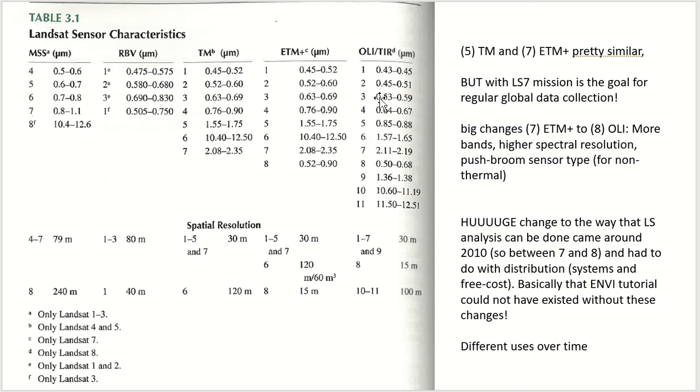And so these have to do with more bands. The bands don't match up neatly because there's a coastal blue, coastal band here, observing reflectance over a rather narrow wave band, 0.02 micrometers. Band 2 in OLI corresponds to band 1 in TM and ETM+, a little bit narrower, so just a smaller max at 0.51.